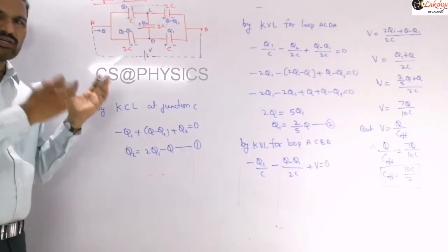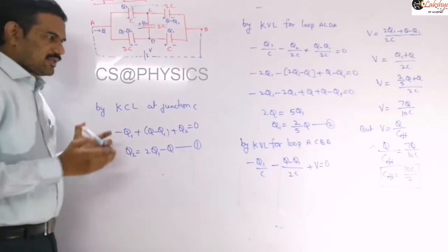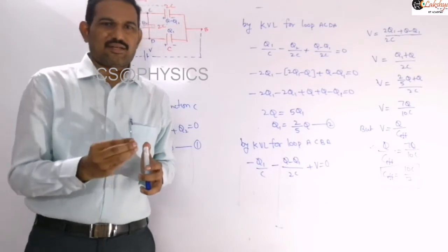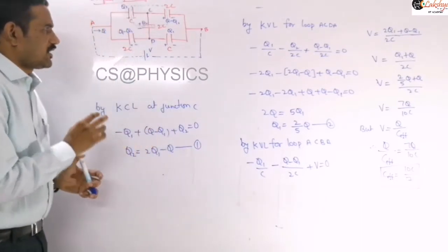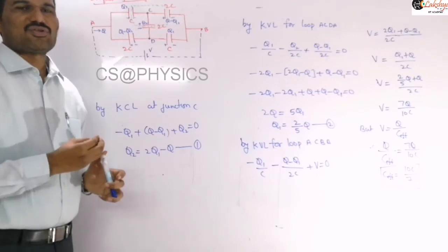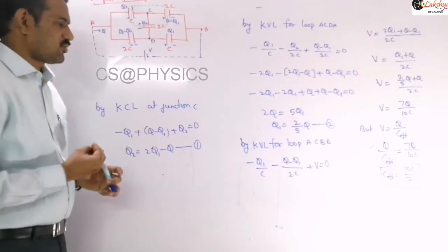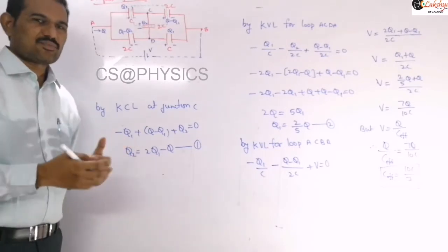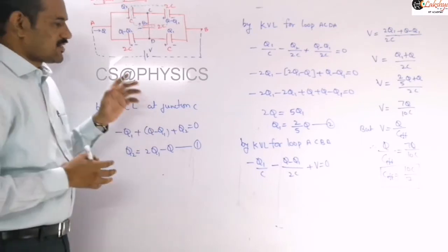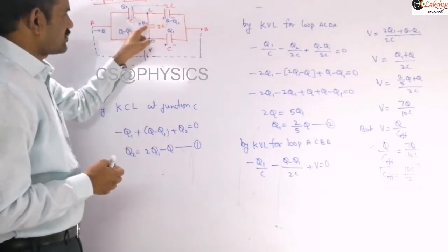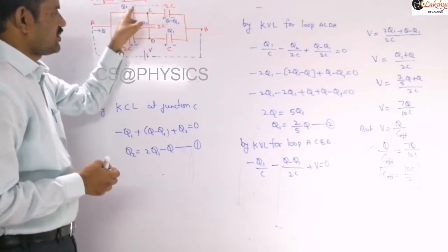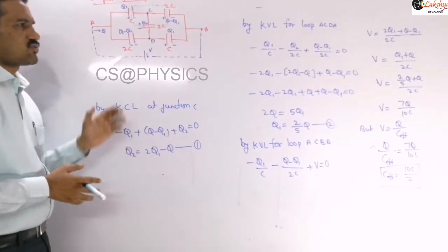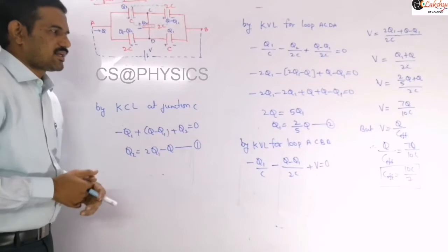Like I1, I2, which we consider in resistive circuits. Similarly here, first after taking this charge distribution, we need to write Kirchhoff's first law to get the relation between Q1, Q2 and Q3. Whatever variables we are assuming, to write the relation among them, we need to write Kirchhoff's first law here. Then you will get some relations between the different charges we are assuming. That is the way of writing here. Here I am assuming the total charge on this isolated system will be 0. Just equating that, we get this one relation. So just by applying Kirchhoff's law, we get another expression here.